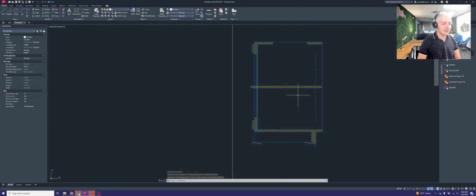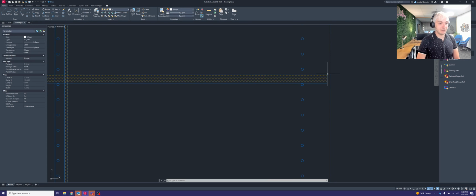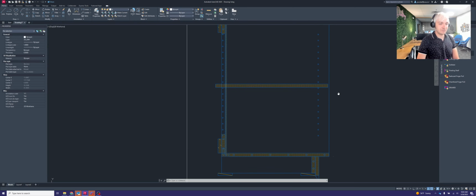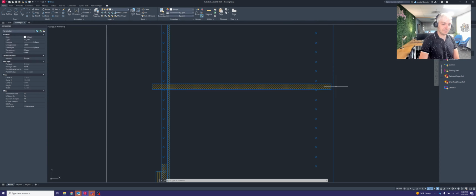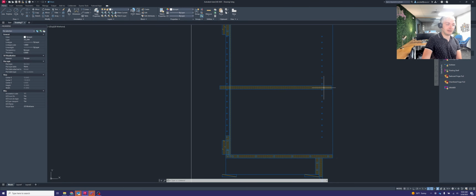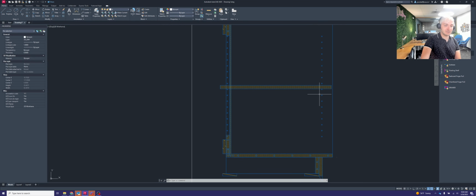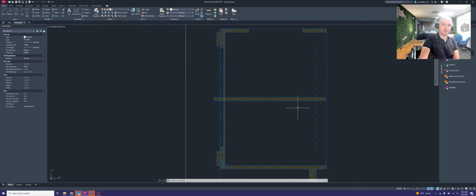and that's made so you can drop that shelf right there. There is a small 1/4-inch gap between the front of the cabinet and the front of the shelf. That is intentional because if you had the shelf all the way to the front of the cabinet, it might hit the back of the door. And also it would be hard to line this up to be perfect with the front edge of that cabinet. It might stick out a little weird. So we don't ever do that. We bring this back 1/4 of an inch just to make sure we don't have any issues there with alignment.